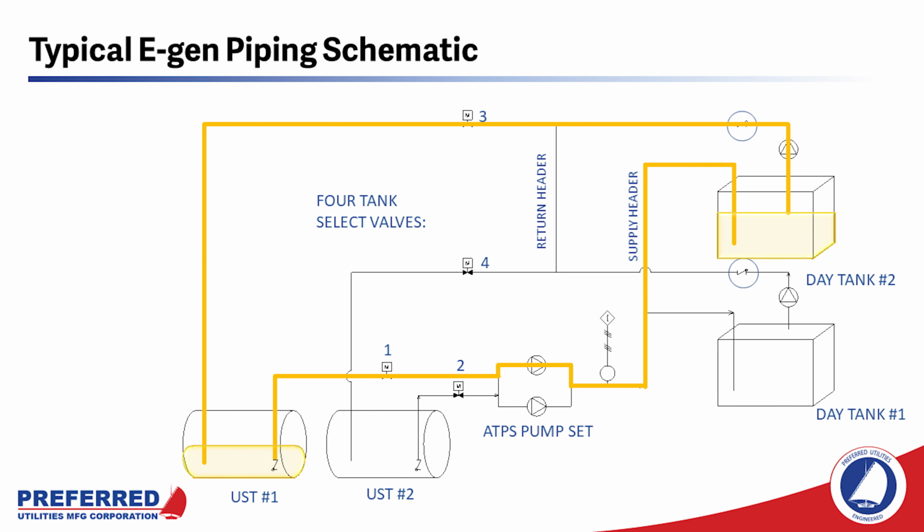So the return pump will have a hand-off-auto switch attached to it. Energize that return pump, let it pull the oil level down to the pump on switch, and make sure that the supply pumps come on automatically and top off the day tank like they should. So even when you have underground storage tanks and gravity return will work, we still recommend return pumps.